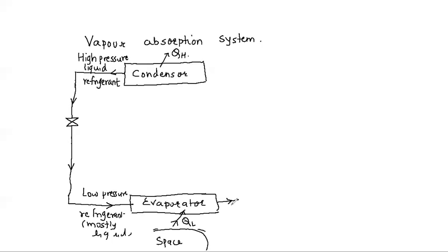And as a result of which the refrigerant would boil, it would evaporate. And what you are expecting here is low pressure gas refrigerant. Okay, it is not the liquid now, it is a gas refrigerant because it is converted to the gaseous state. So gaseous refrigerant, or you can use the term vapor also, right? But it is not a vapor in the sense that it does not have any liquid. So it is a gas refrigerant which is at a low pressure.